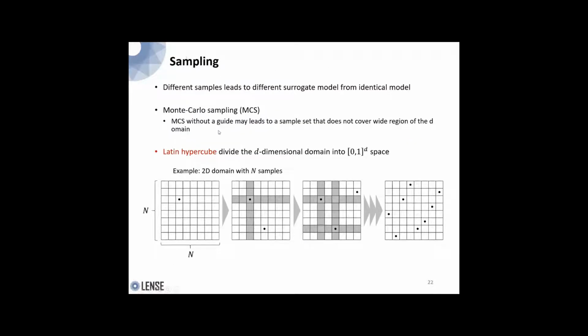And I'll come back to that later. Now, sampling is important also. When you form a surrogate model, you create samples. How do you create samples? Well, you want to create samples where the operation range, the input range that you're interested in, would be well covered, essentially. If you have a wider, higher dimensional space, you will need more samples in general, right?